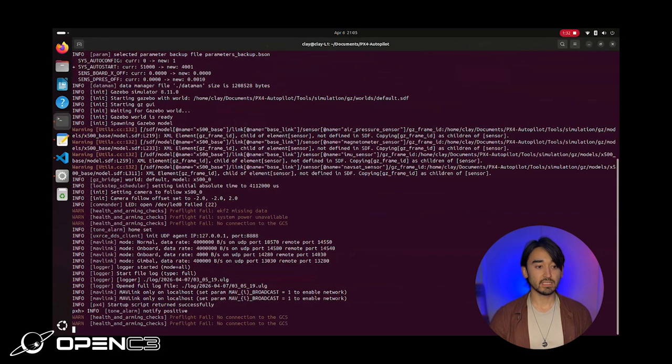And then what I'm going to do is start a stream using MAVLink start -x -u 14560 and then -o 14552, just some ports that I'm opening for a UDP interface, the 14552 being the one that we'll be sending out to Cosmos. And then I will start that.